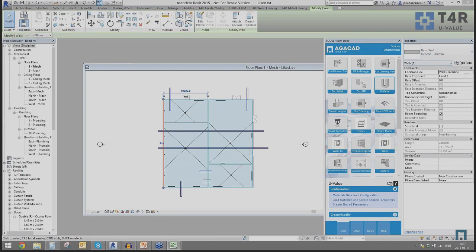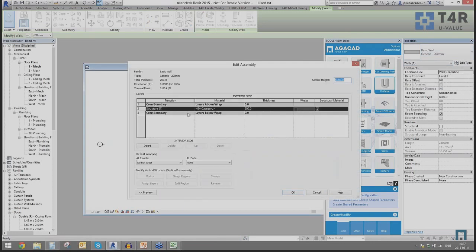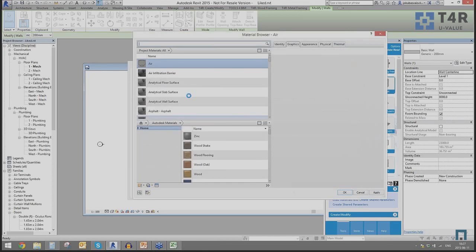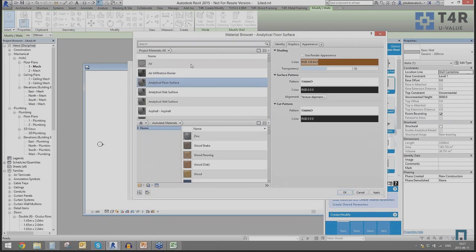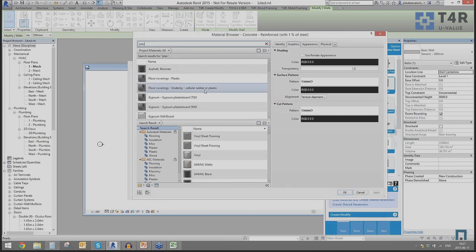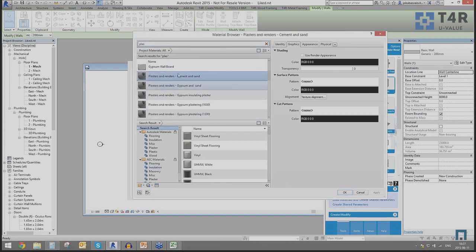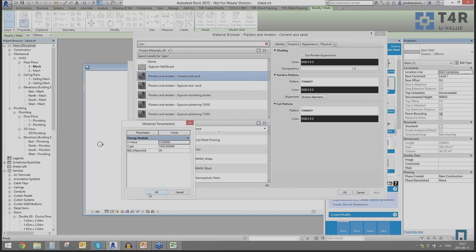While I'm clicking on the wall, I'm going inside the wall, to the structure, and to the layers, to the material of the layers. So I am able now to use that Excel plaster or something like this from my Excel sheet. For example, plaster.